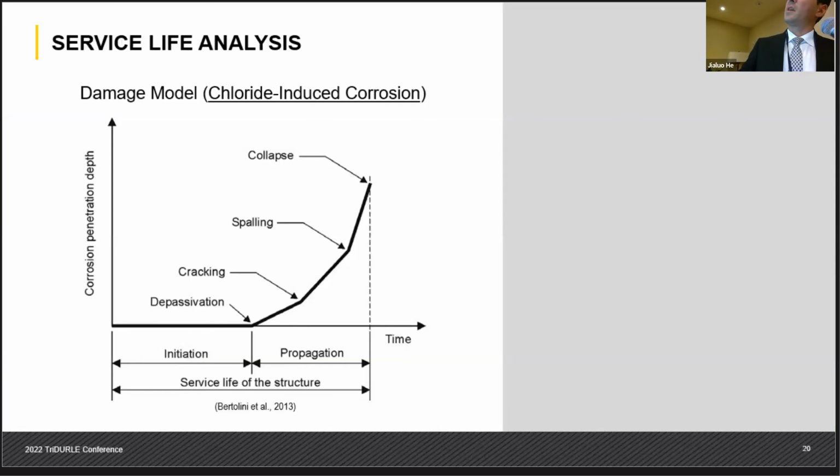And then service life. When we get into service life, now we get into a tool. It's a tool that helps you understand the performance of that concrete under a certain condition. Now, I always say, you can use the same level of exposure conditions with the same concrete, the same design, and there's always one part that is managed by the design engineer: the reliability, the risk analysis, right? A 50% reliability design is not the same as a 95% reliability design. And all of that is part of the input on a service life design, right? So you need to understand also what level of risk you can tolerate, right? And that needs to be established at the design level, at a client level, because the cost of a structure is not going to be the same at a 95% reliability and a 50% reliability.